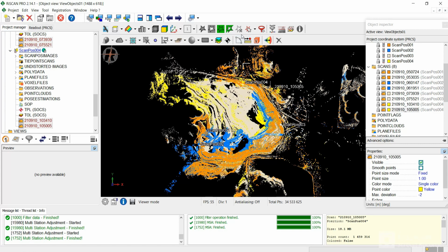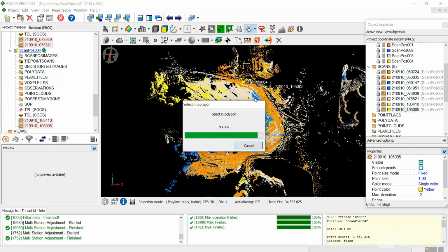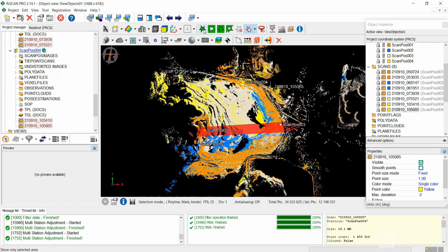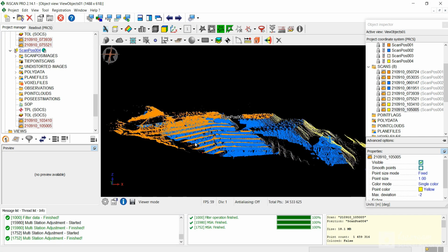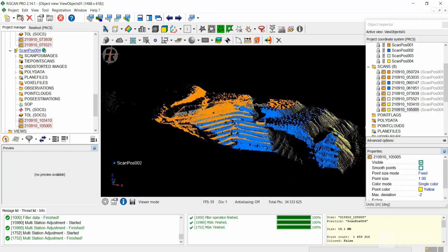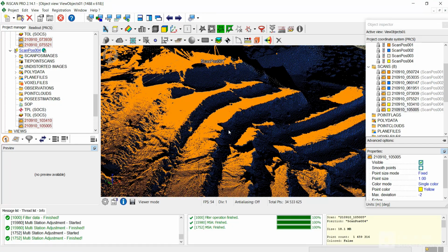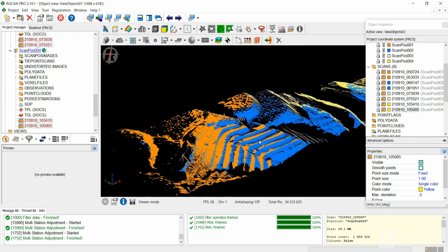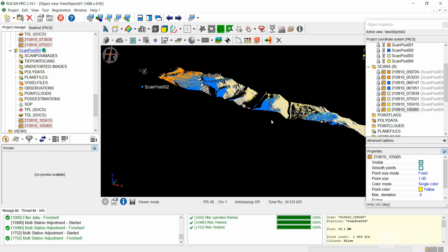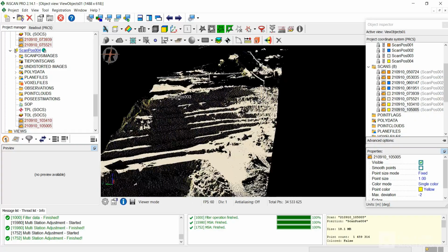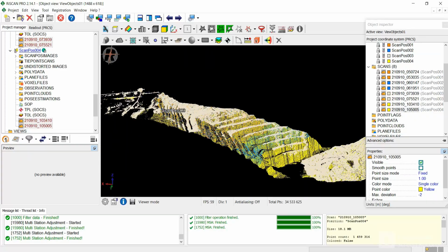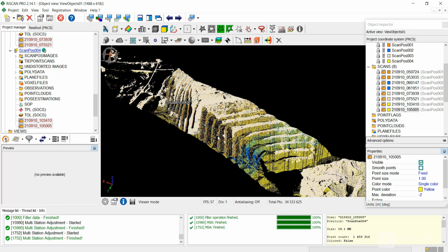If I take any strip and see that selected data only, and deactivate the selected mode option here, and then look for any inconsistency, see, earlier also we were not able to see the inconsistency with our naked eye, and now also the data is quite similar to the automatically registered data. Nevertheless some optimization has been achieved, and now the data is optimized to 0.005 meter. Earlier it was 0.09 meter.